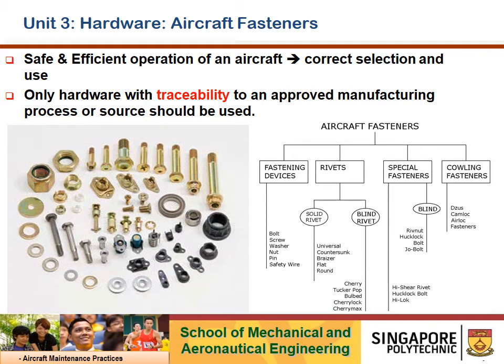Aircraft fasteners. They are to be correctly selected and used as per the requirement of the Aircraft Maintenance Manual and Illustrated Part Catalog. Only hardware with traceability to an approved manufacturing process or source should be used on aircraft installation.